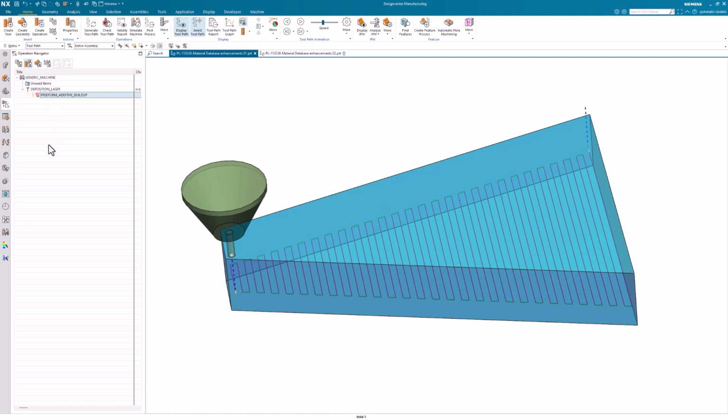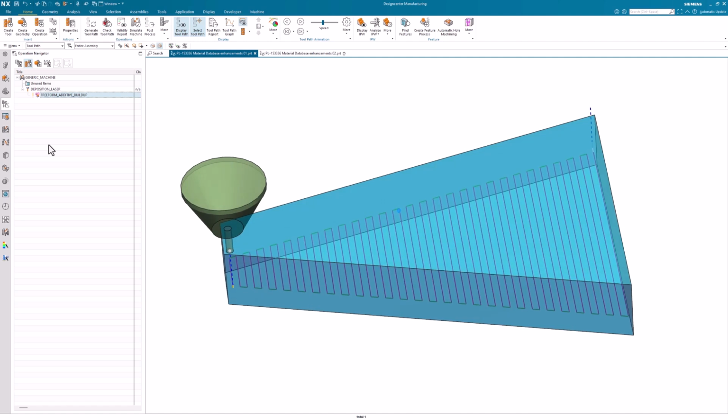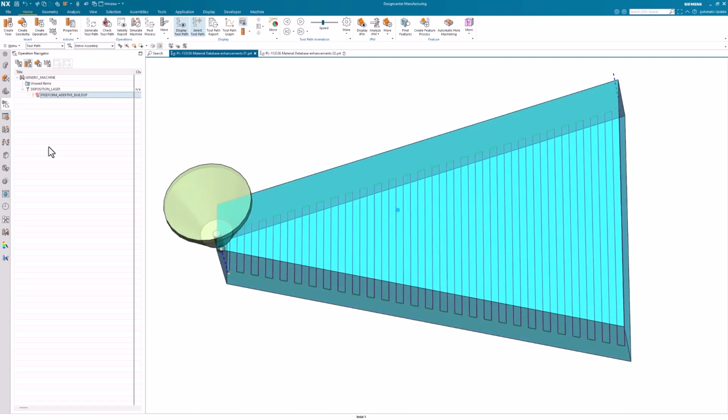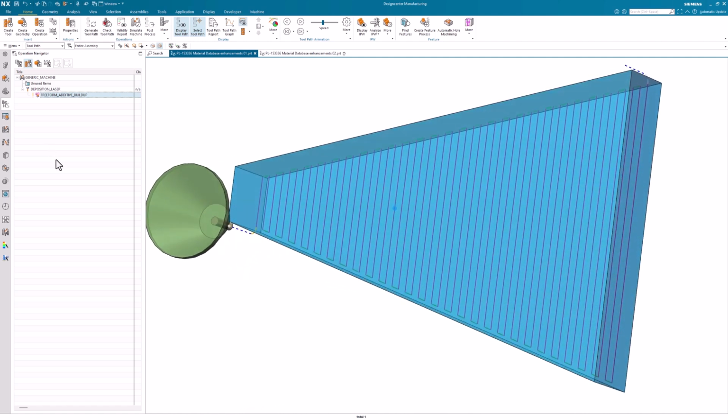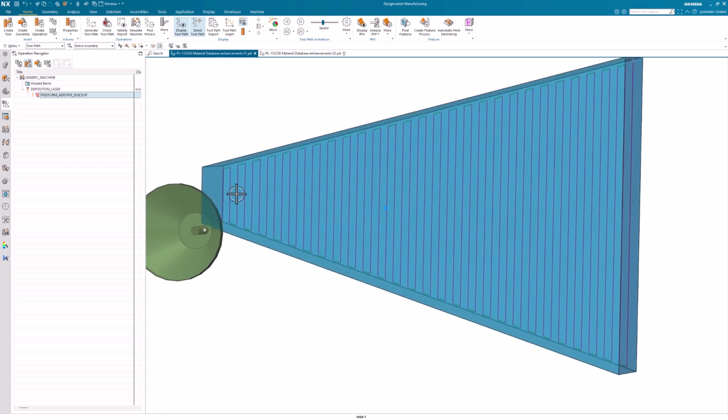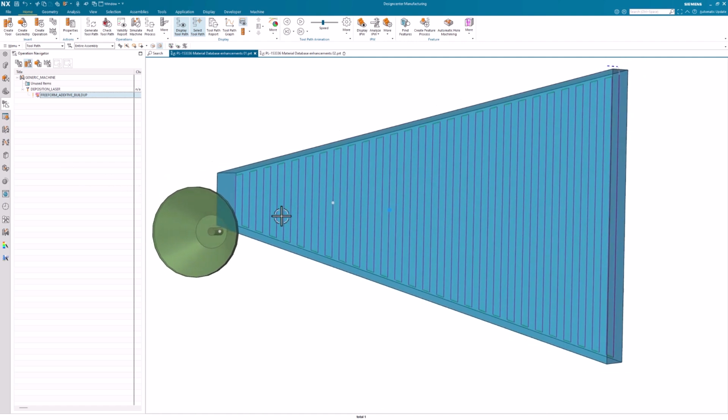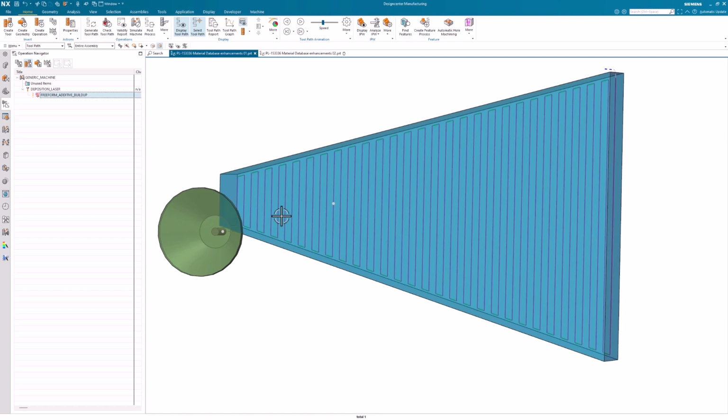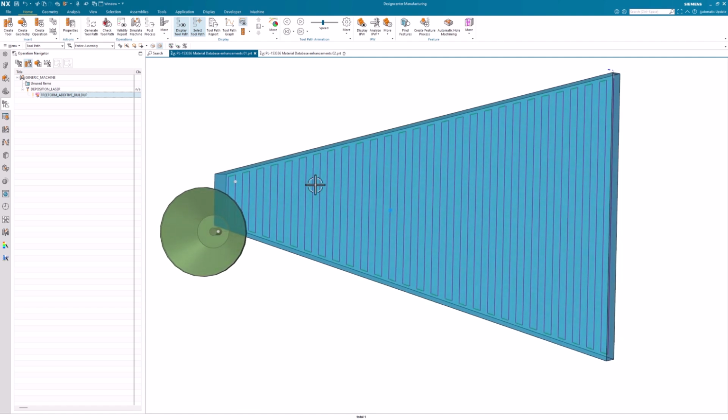When printing parts, custom process parameters are often used for different portions of the calculated cutter path. One new build style rule option is to create custom process parameters based on the length of the individual pass in the cutter path. Looking at this simple trapezoidal-shaped part, a machine operator may wish to use different process parameters where the pass is shorter, shown on the left, from the parameters for the longer path sections shown on the right.